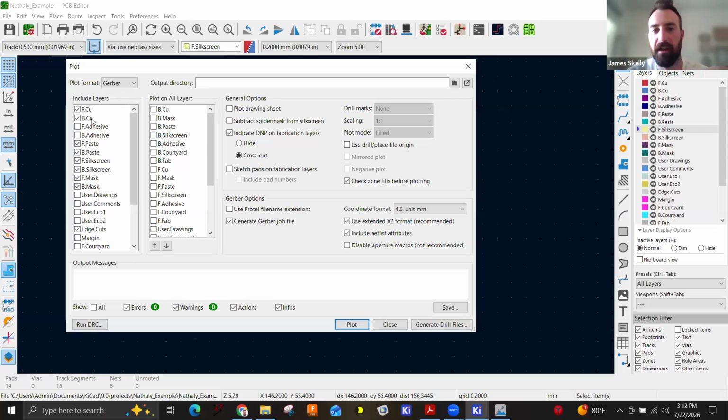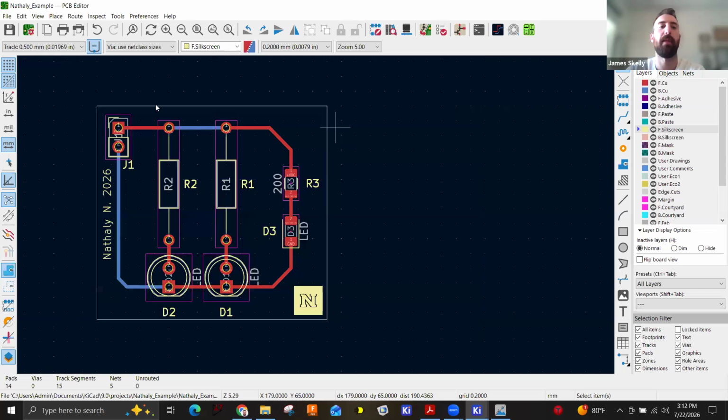That's where all of the pads are actually at. The way that a PCB is actually manufactured is that the entire board starts out as copper. It's like copper, and then there's a layer of insulator, and then there's another layer of copper. And what they do when you tell them, this is my board, is they actually go and they etch the copper away everywhere that you don't have it.